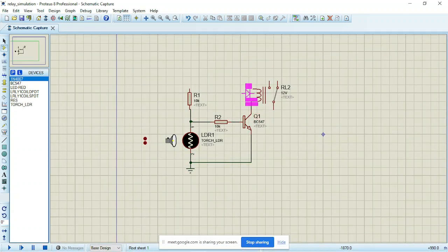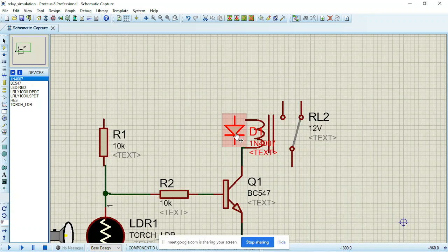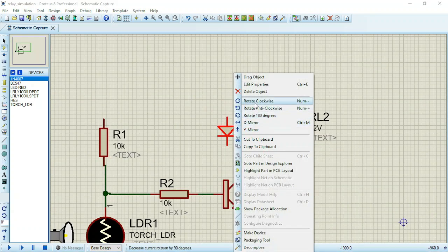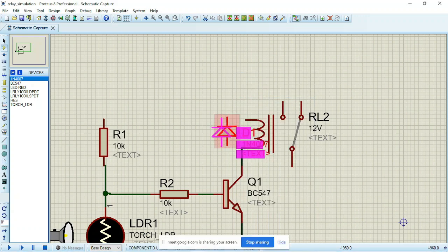Once you turn off any circuit that has a coil or an inductor, definitely there's going to be backflow of EMF. So you want to connect this diode so that once you turn off your device, the diode will block the backflow of the EMF. It will not flow back to your circuit and damage something. So that's why we are attaching this diode here.